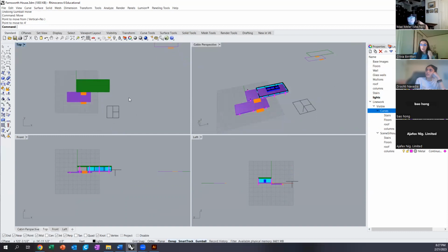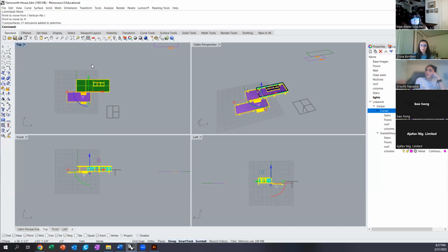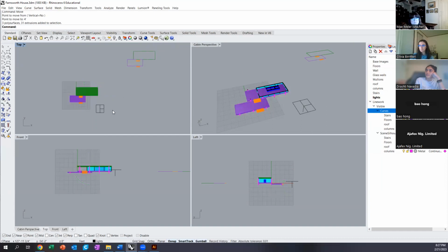And as we've discussed by now, if I use the Make2D command, if I highlight all of this in my top view and Make2D again, that floor plan is not going to show up as it's showing up in perspective. It's basically going to create my roof plan again. So what do I need to do? I need to select my clipping plane, and I need to mess around with its properties.